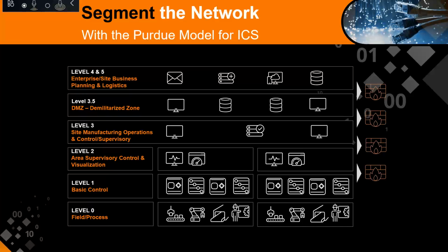But now that we do have internet and we do have enterprise IT, under the influence of Industry 4.0, we increasingly start to connect the OT domain to the IT domain. And that's where level 3.5 comes in, because if you want to connect a high secure domain like the industrial network to a less secure domain like the internet, well, best practices dictate that you need a demilitarized zone. And that's what level 3.5 provides. So here you will find devices that can be accessed from both the OT domain and the IT domain. But communication between OT and IT should always go indirectly.